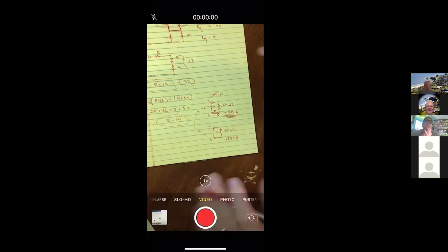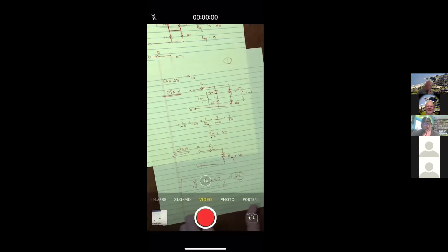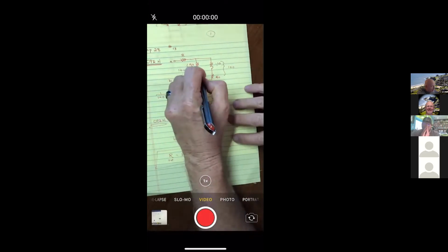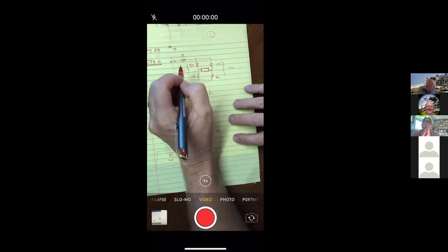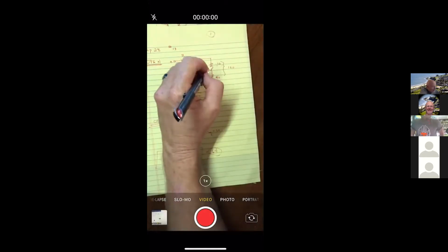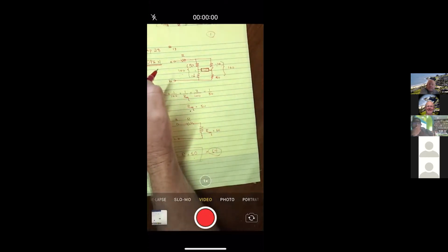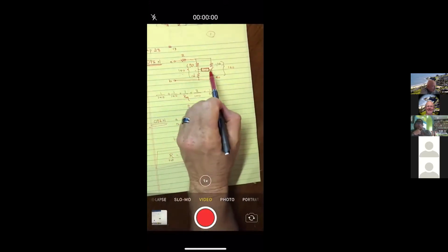Oh, well, no. Okay, let's go back to our original circuit. They're not necessarily giving more voltage. They're the switch in here. So if I come back to the original circuit right here, and I put a photoresistor right here, okay? Now, what a photoresistor is, when light hits it, it actually becomes a pretty good conductor. So during daylight, this would be a conductor.